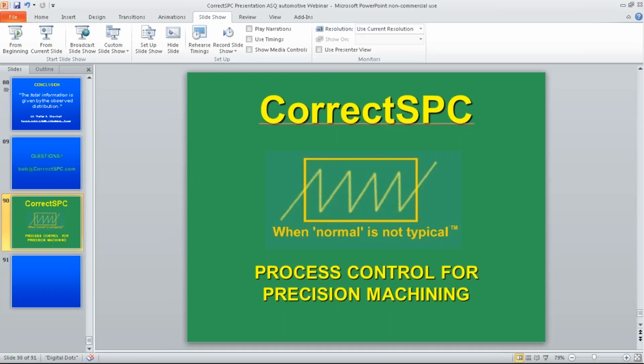Okay, here's another one. You mentioned once tool wear is a special cause, but it's truly a common cause, correct? I'm sorry. If I did, I meant it is a common cause because it affects every part. Other people have identified it as a systemic special cause, but you can't remove it. So it's common, it affects every part, and it's intrinsic in the process, so it's a common cause.